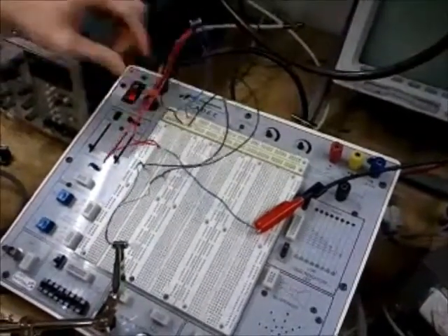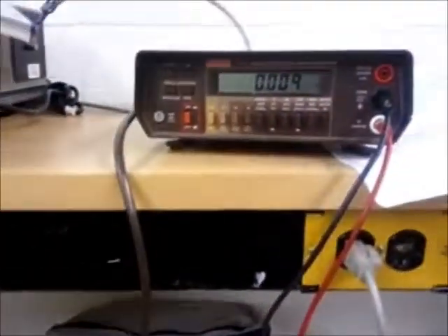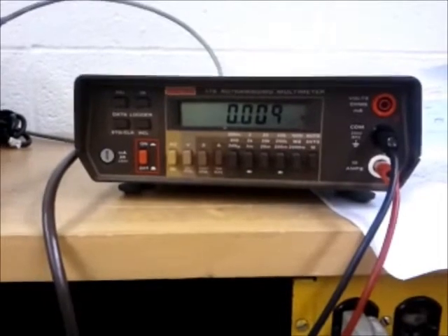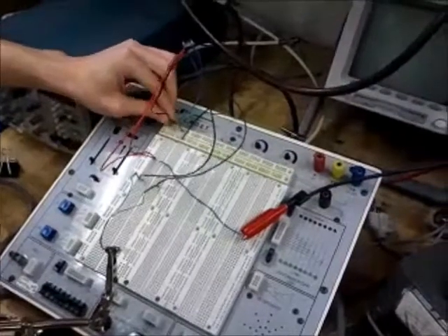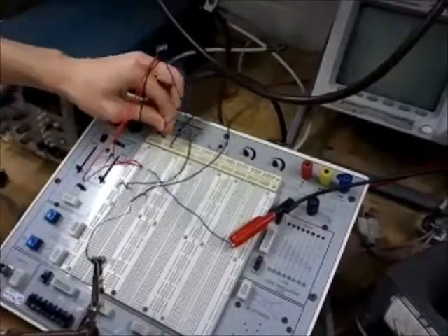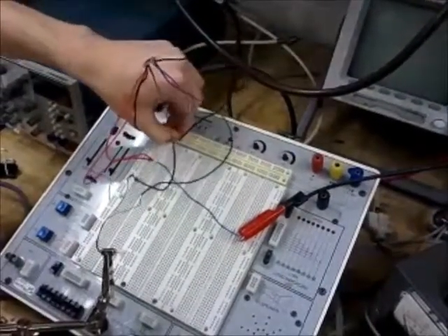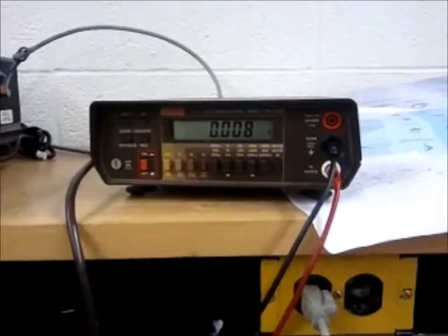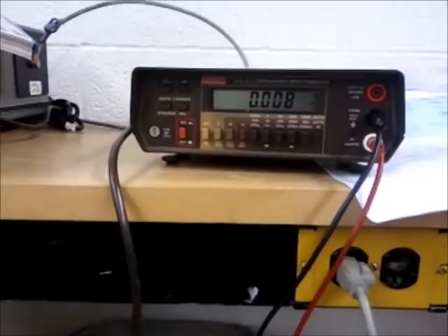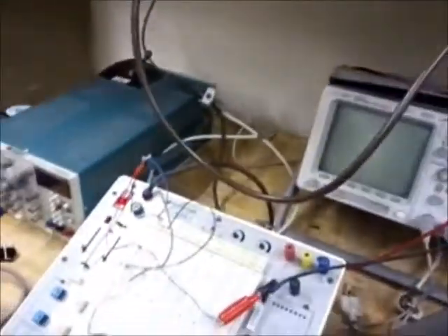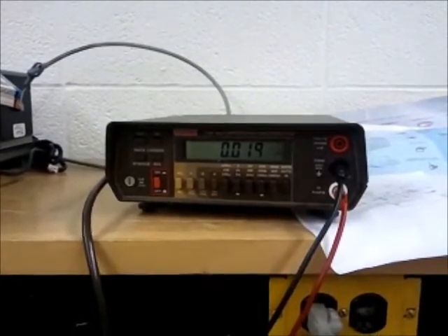Okay, we're going to test the typical current and max current of our motor drive circuitry. So right now the motor's driving clockwise, and we're going to see how much current the circuitry is pulling, and that's around 10 milliamps. Now we're going to reverse it and do counterclockwise. It's pulling 8 or 9 milliamps. And finally we're going to test the max current or the stall current of our motor, which is around 19 milliamps.